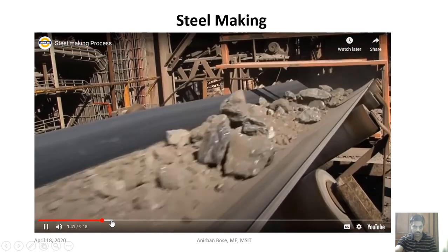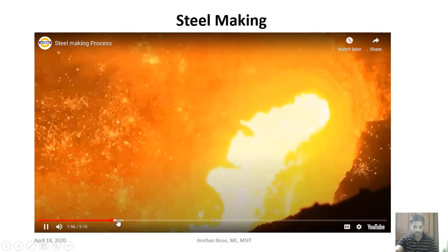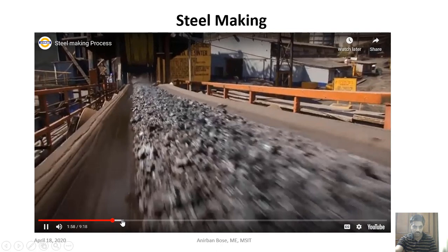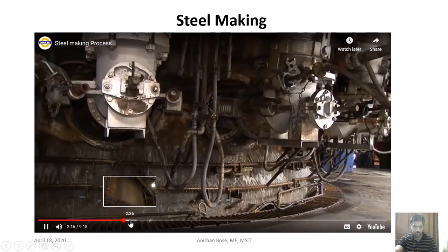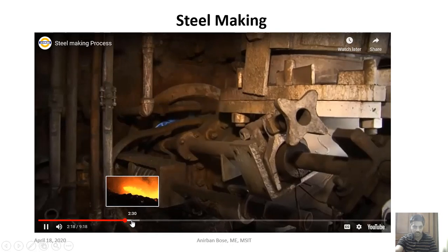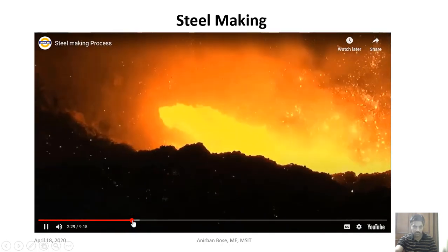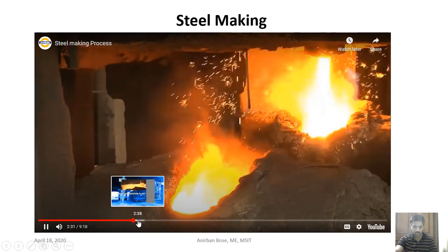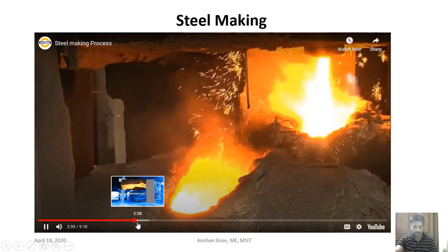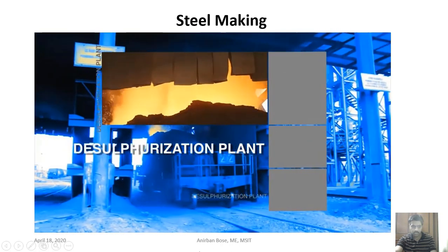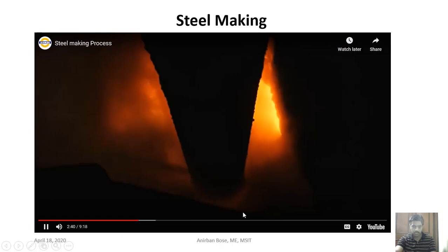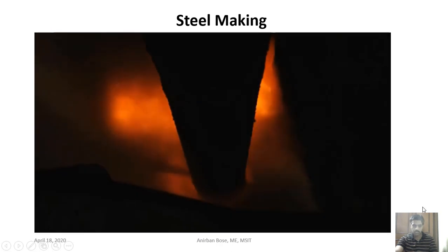Processed iron and coal are the basic raw materials for producing pellets and sinter, which are stored in the hopper facility located on the top. Hot air is introduced under pressure into the bottom of the furnace, blasting the coke and smelting the iron ore. The iron is drained through tap holes and troughs and emptied into 200 metric ton capacity torpedo cars. In order to eliminate sulfur content, reagents such as calcium carbide and magnesium are applied to the pig iron in the desulfurization plant.